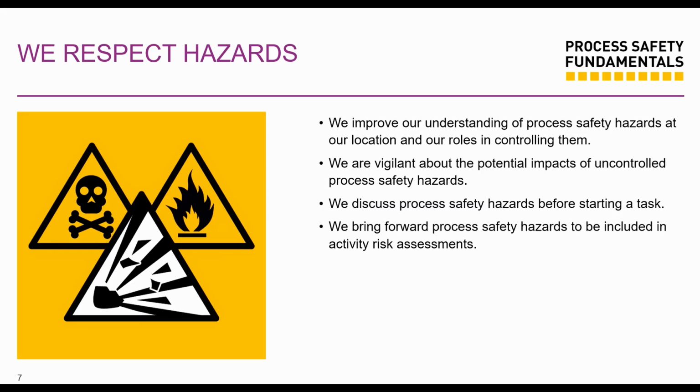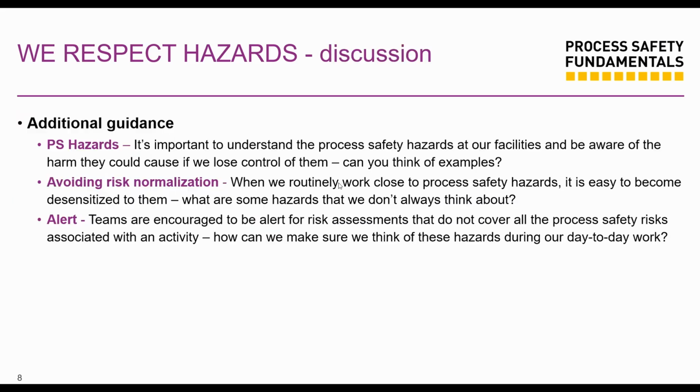So you need to understand those hazards, that, hey, maybe we have H2S here. Maybe we need to actually come with our gas testing equipment, or you clean a tank that probably had benzene. Benzene is hazardous, and you believe it's empty, but you don't treat it as a hazardous environment, and you go close to that tank and you're performing some hot work, and you have vapors igniting from that place. So that's also another. You should have done your gas tests in those areas.